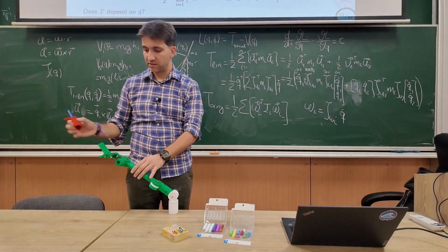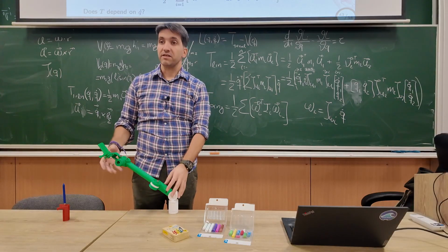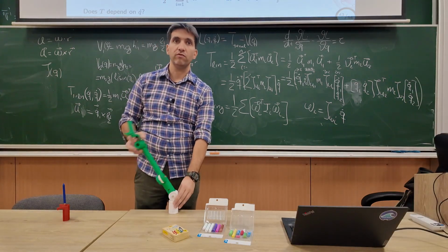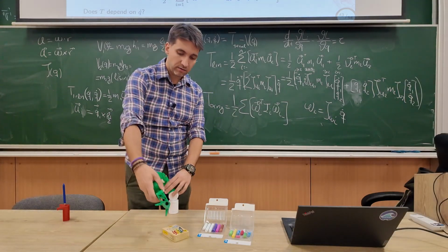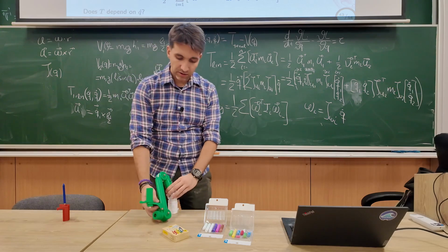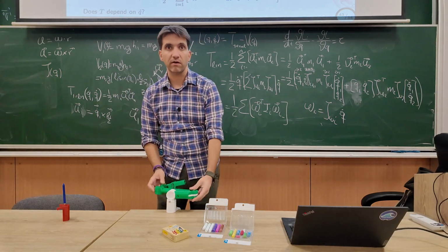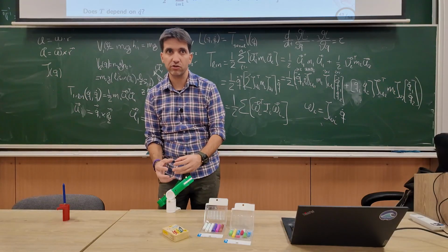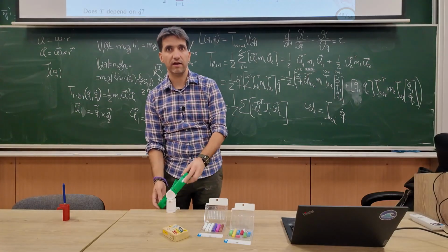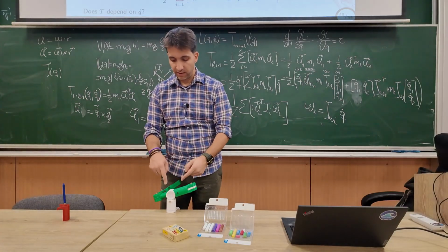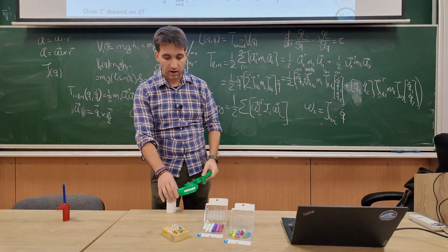And let's try to visualize this. We have the system and it has some inertia when, let's say, this joint moves, right? I will have a different inertia if the robot is folded like this and then this joint moves. The masses are more concentrated, so obviously the angular momentum is less. The linear velocities of the links are smaller because I have less arms, basically.